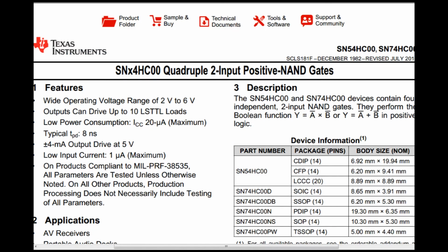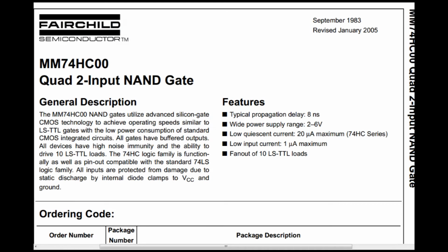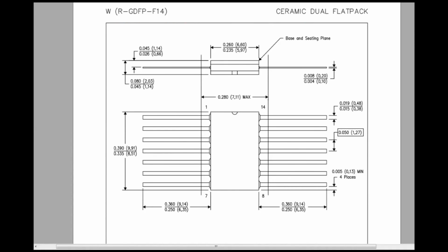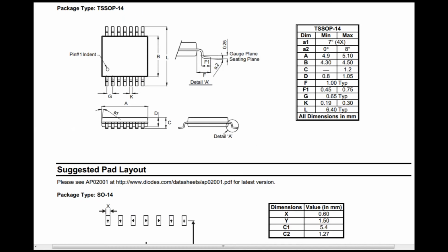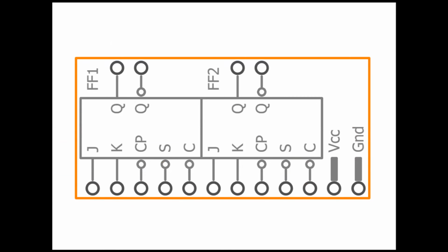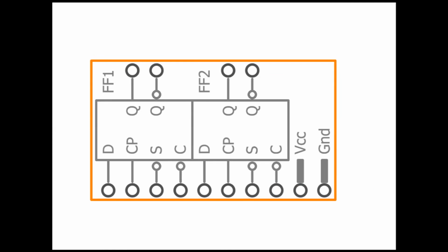Data sheets of different manufacturers will be studied for the main function of the chips. Then the package forms will be collected. The pinout variations will be decided for best usage. Package will be at the bottom of the board. Traces are drawn as wide as possible for power and heat dissipation. Silk screen will be illustrated at the top of the board. All the information about the package will be placed as symbols or characters on the board.